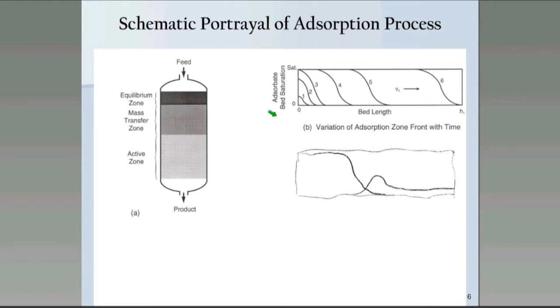So let's take a look at partway through the adsorption cycle. Let's look at step number 4, where a stable mass transfer zone of water has been established. If we take that snapshot in time and look at this hand drawing below, this profile represents the adsorption of water. In this section of the bed, it's all active molecular sieve. What we show on here is a profile of hydrogen sulfide that has loaded on the active portion of the bed. The reason for this little increase in concentration is due to the fact that the water has displaced the hydrogen sulfide and the partial pressure has increased, so therefore the loading of hydrogen sulfide is higher in this portion of the bed because it has seen a higher partial pressure.